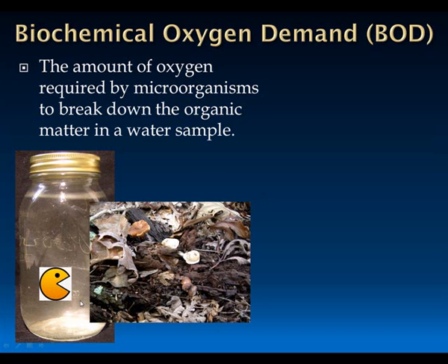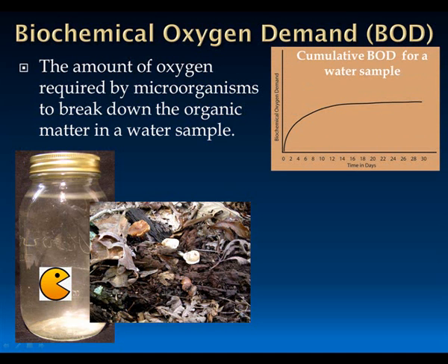And so if you've got your little microbes in your water sample here that are going to work to break down that carbon, they need oxygen to do that. And so we measure that with biochemical oxygen demand. And so this is a graph of the BOD, or the cumulative biochemical oxygen demand over time.